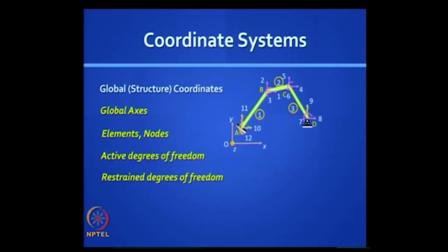So with this we have captured all the displacements at the different joints, D1 to D12. Some of them are active, some are restrained, is it clear? And by the way, restraint does not prevent you from including support settlements, but then it is still a known quantity. Usually it is 0, but it can be non-zero.